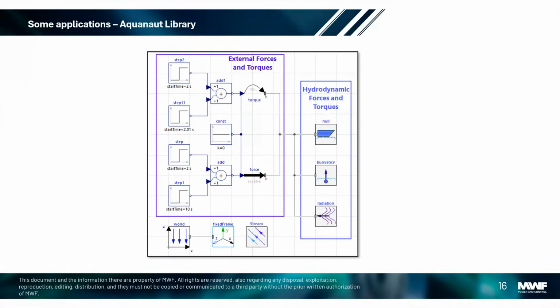And just like in the previous libraries, it is 100% compatible with the multi-body library. It allows one to run simulations and verify everything visually, just like those animations that I presented before. And it is very interesting to see. Also, we have the models of the waves that are provided as inputs for this model. We can see if the boat is floating just like expected according to the motion of those waves.